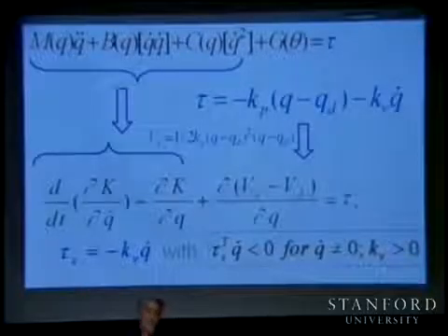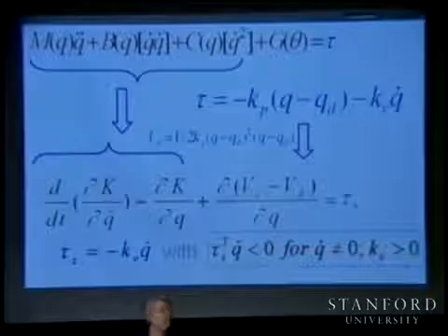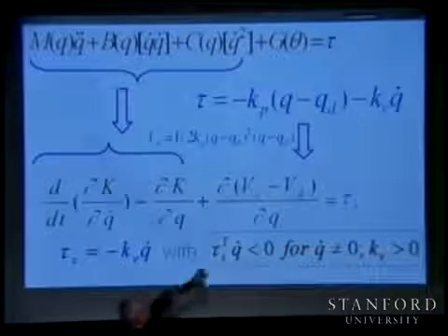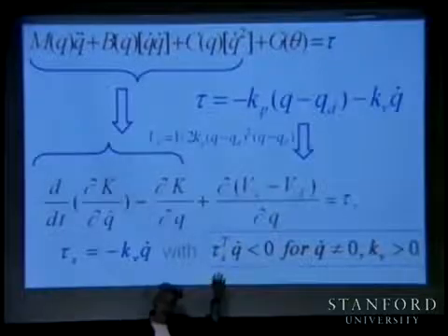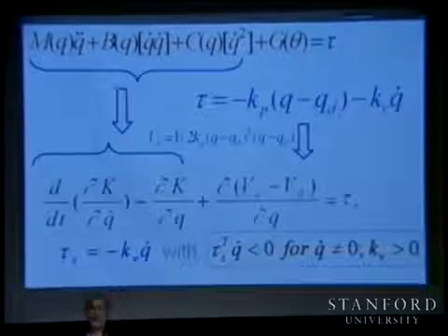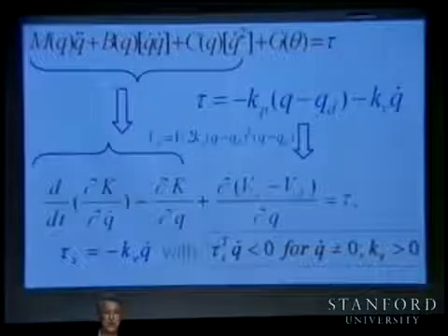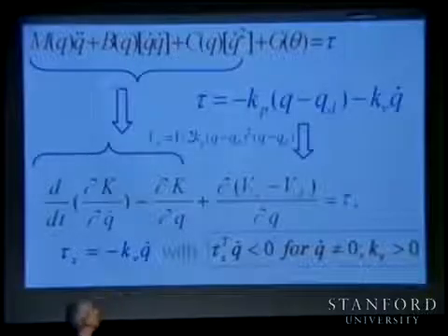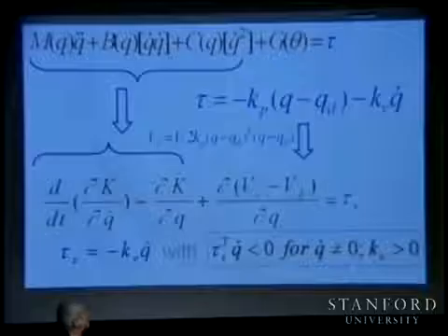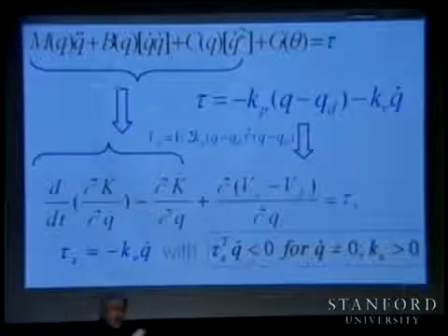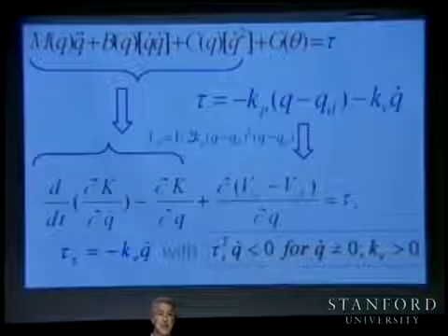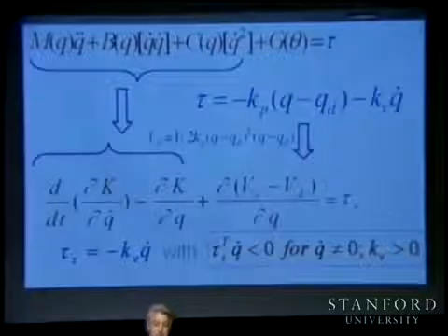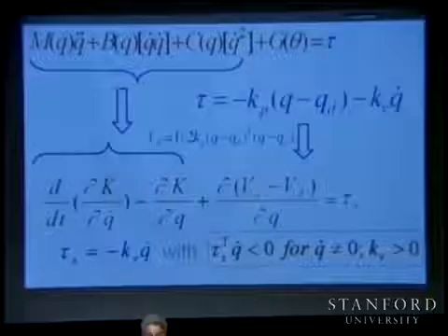You can move and reach that goal position, and you will have a small offset because of the gravity. You can, in fact, put in Vd some compensation of the gravity and take it out, so you can reach that goal position. But if you are tracking a trajectory, the performance is not going to be good. So how do we evaluate our performance?